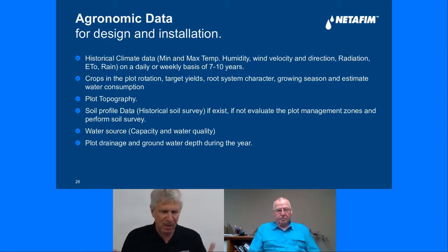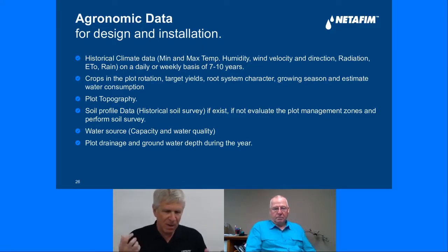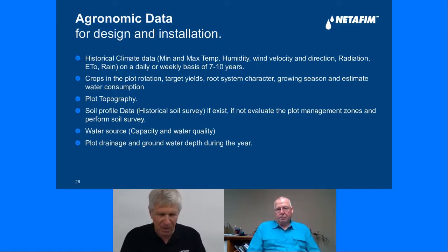How much water do I have in different months during the growing season? And what is the water quality? The water quality is not only the chemical water quality, but also the physical water quality, because I can use it to understand what kind of irrigation system I'm going to put in, like what kind of filters. If I have a high organic load, or high suspended solids, I need to understand it in order to design the best solution for a certain problem that I have with the water.